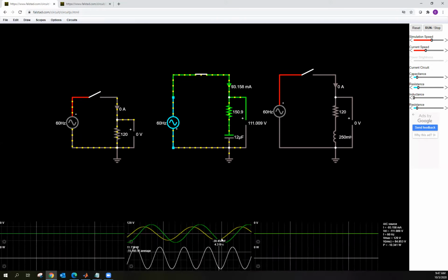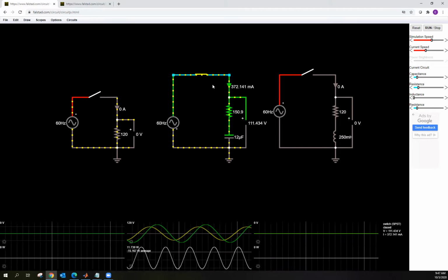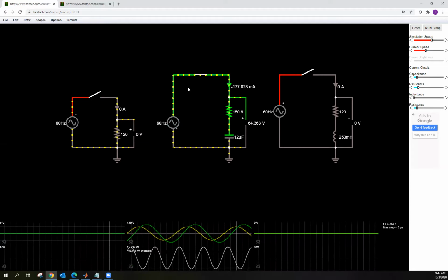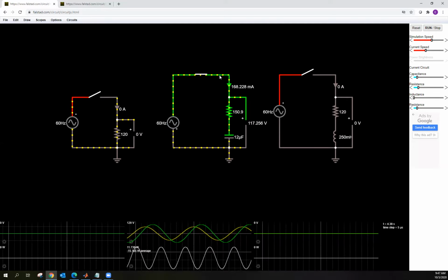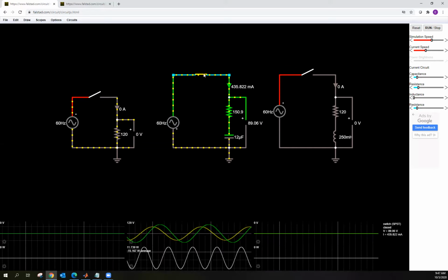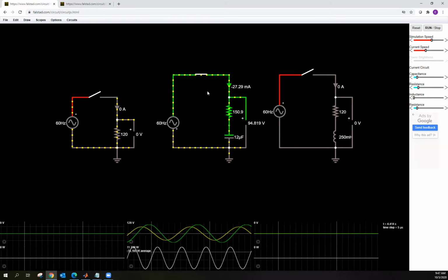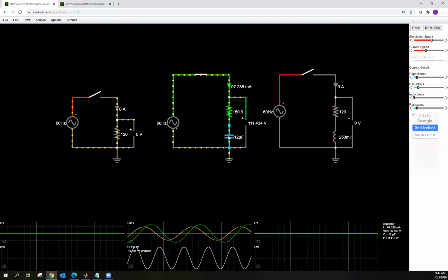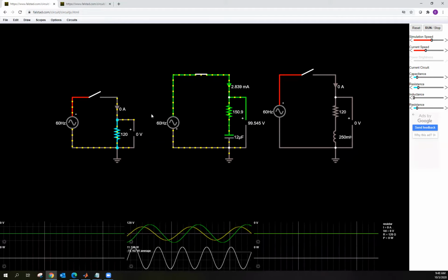Okay. All right. And then again, last thing is you can look at the yellow balls that are moving, and then the voltages, and you can see that the current leads the voltage. So the yellow starts moving and then it changes color. So the current is leading the voltage. And this is all coming from this spring-like capacitance effect, because this is acting like a spring, okay? Resistors are acting like dampers.